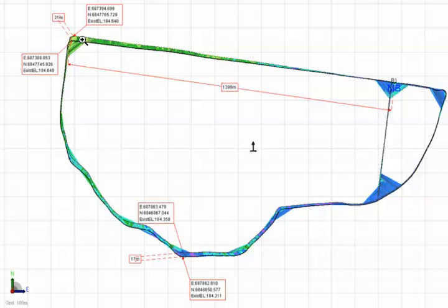And as you can see, there is a significant difference at the furthest point away from the master benchmark, which is about 1400 meters, is 21 meters difference in the horizontal. So those lines should overlap perfectly if the coordinate systems matched perfectly.